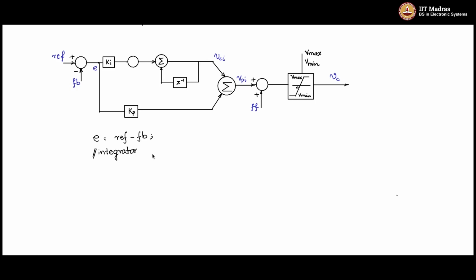So before I write the integrator, I am going to include one more block here for taking care of anti-wind-up. Now this is not a summing block, this is a product block. Remember, this is a product block, and I will give in a variable k clamp. So I'll explain. If k clamp is 1, whatever input is passed on to the accumulator accumulates in a normal fashion.